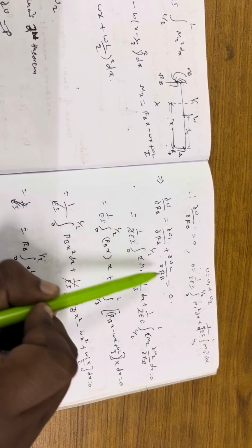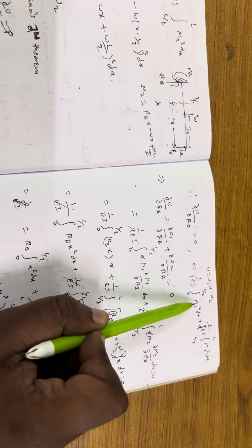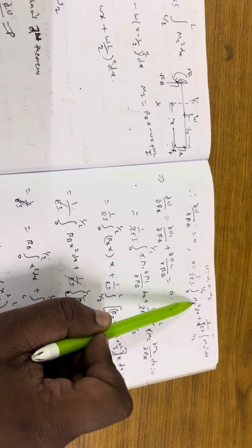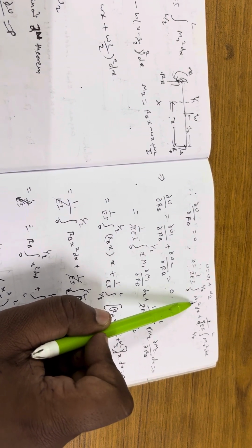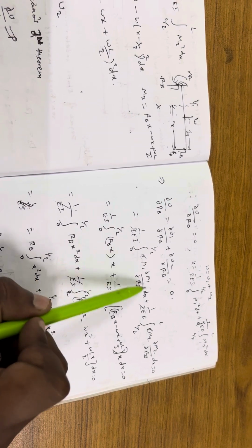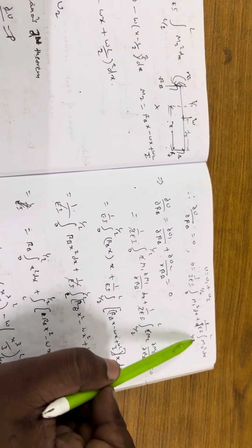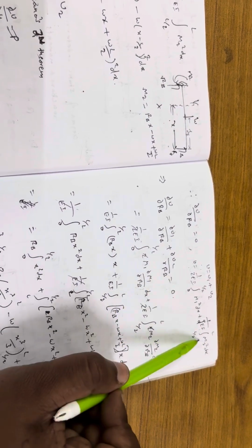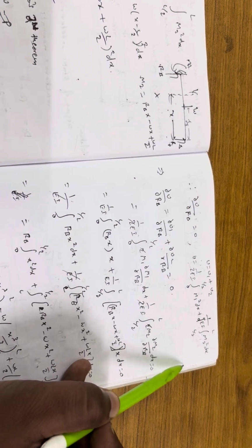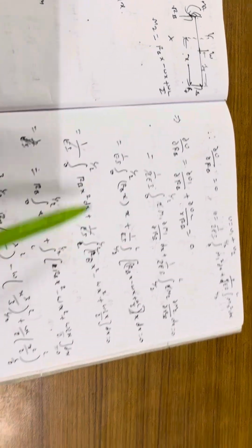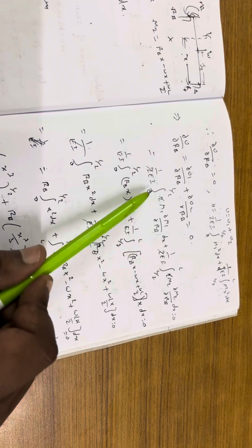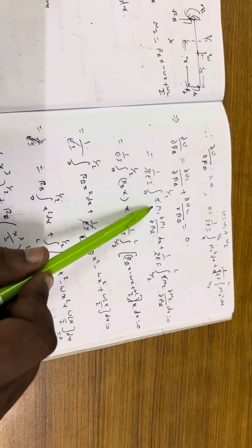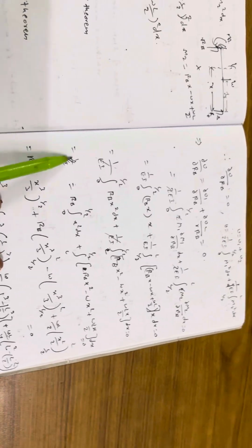Okay, now this one, if I partially differentiate it, it will become 2m1 into ∂m1/∂RB, plus 1/2a integration from -L/2 to L/2, 2m2 ∂m2/∂RB dx, equal to 0. If I simplify it, the 2 will get cancelled. Then I will substitute the m1 values which we have already calculated.